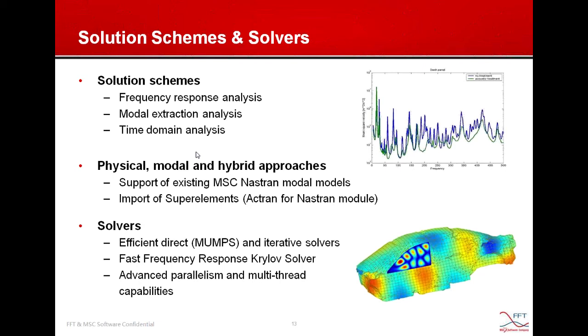And different types of parallelization are also available in Actran. The computation of a single problem can be spread over different processors using different strategies of parallelization, from frequency parallelization to domain parallelization or to finite element matrix parallelization. Actran also features multi-thread calculation capability to speed up solution time.